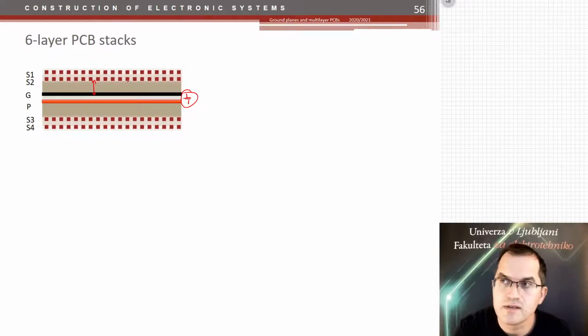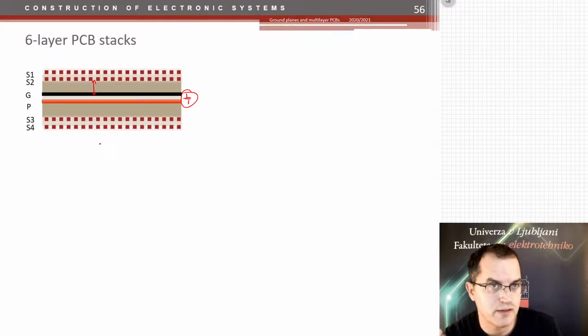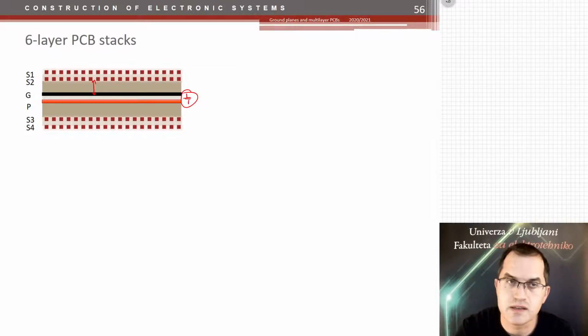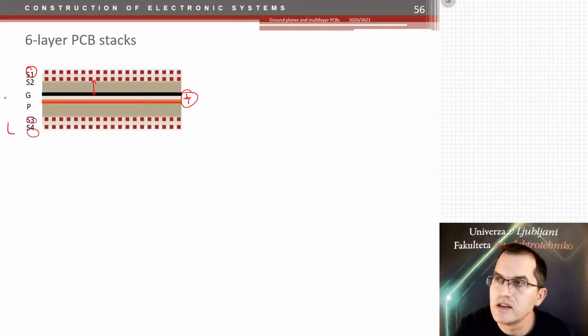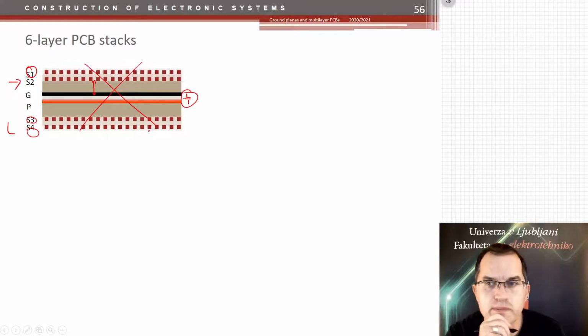The impedances of the tracks could not be made small enough for the required impedances with a usable width. And layers 1, 3 and 4 are for low frequency signals only. The only layer acceptable for high speed signals would be layer 2. So this is almost not used.